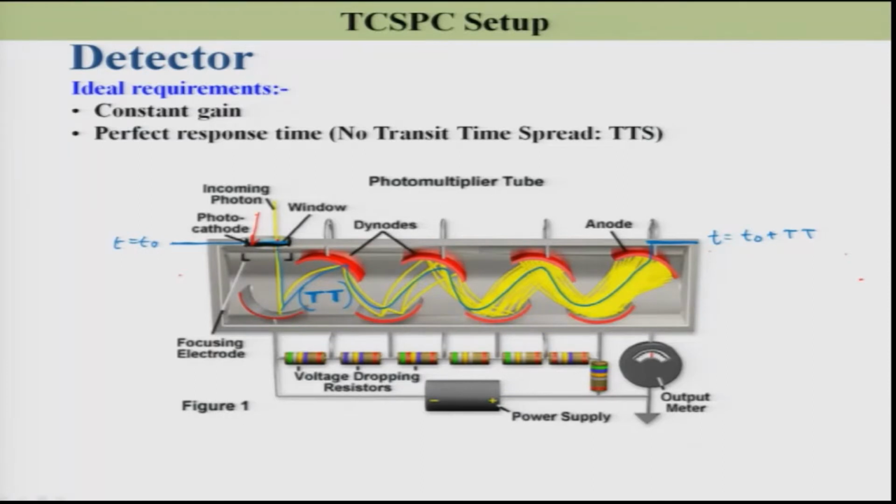The ejected electron will then be directed around this position of the first dynode, or directed this other way. You can immediately figure out from this diagram that the path travelled for the red one and the path travelled for the yellow one may be the same, but in most cases it will be different.